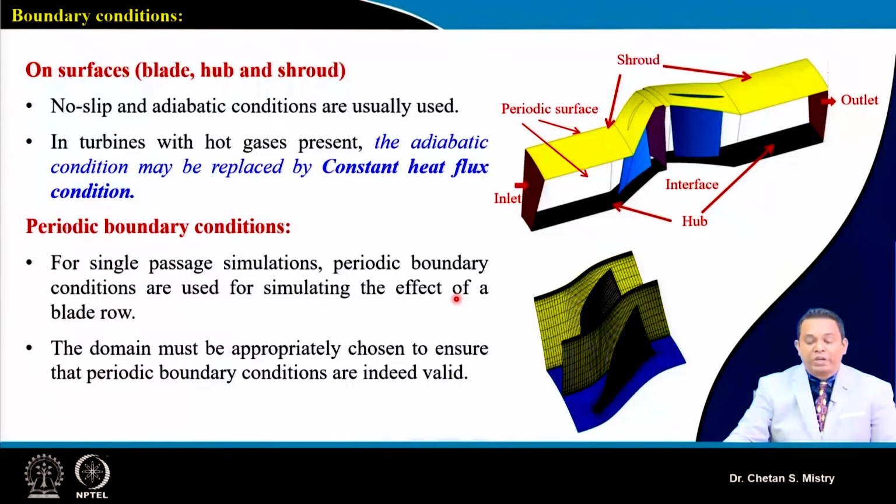So we need to select this condition of periodic boundary condition, or select that surface, or make this periodic surface such that it will exchange the data between these two rotor blades. So basically in order to save computational power and time, we are analyzing our flow domain by using this periodic flow configuration. We are analyzing maybe one blade or two blades. It depends on what kind of flow physics we are looking for.